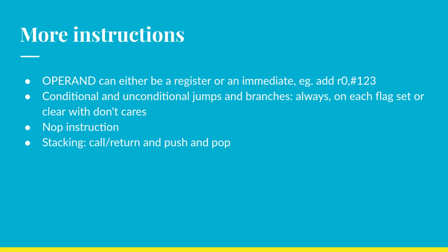So we've got conditional and unconditional branches and jumps, which basically get the flags to test from the instruction word. There's 3 bits, one that sets whether we're interested in that flag, and one that sets what that flag should be. And with that you can implement every permutation you would want. There's a NOP instruction, and of course, because every processor has a NOP.